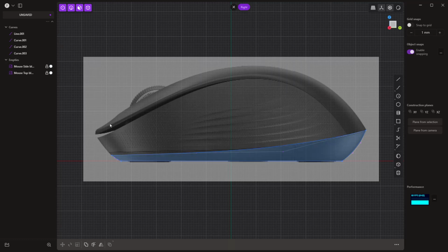Now I need to build the upper section, and I also need to build where the sort of transition line is. Now, in reality, everything on this mouse is smooth. Nothing is going to have a really sharp edge, but we are just going to go for the basic shape. And what's going to end up happening here is we're going to just avoid this gap here where it actually allows you to click. And we're just going to build that base shape. So again, spline tool, we're going to start back here, hold down Control, and kind of work our way forward. And we're going to pick the point in space where we want this to end. So I'm going to go right there.